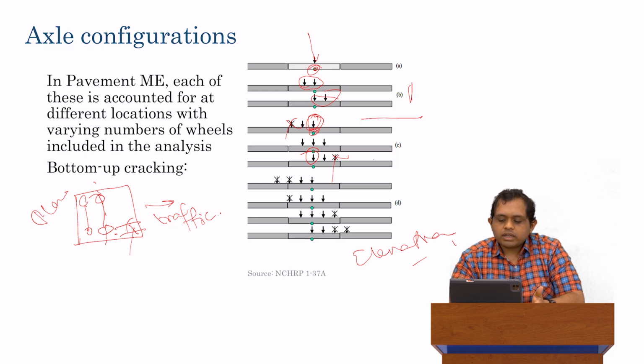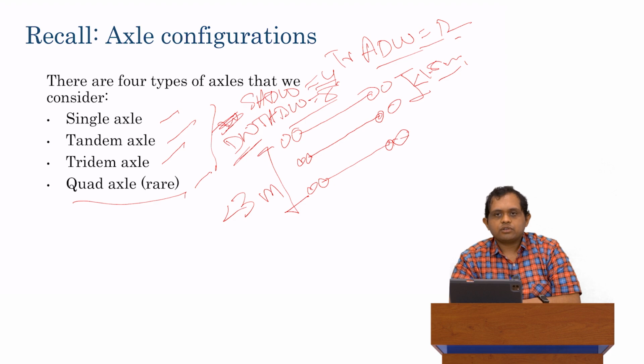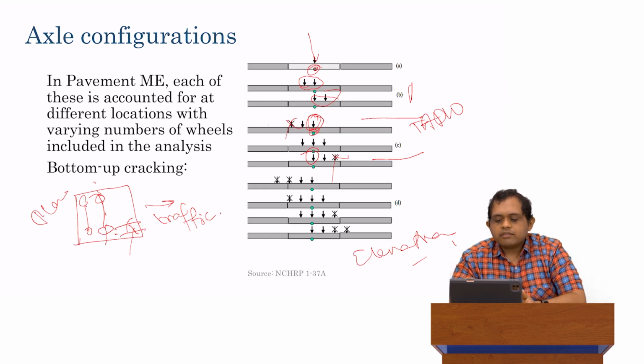That is, in these two cases, not the middle case yet, if we are placing the outer axle exactly on top of the load, then this basically becomes a tandem axle dual wheel, but with the load on the wheel as considered using this calculation. So for example, if the total tridem axle load is 240 kilonewtons, it's tridem axle dual wheel, which has 12 wheels.